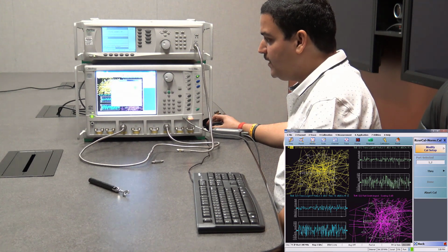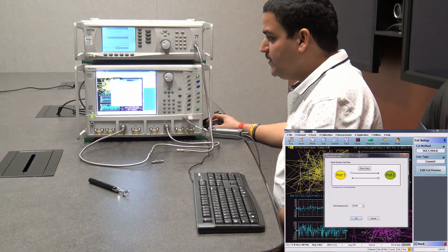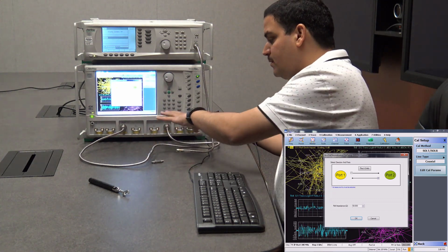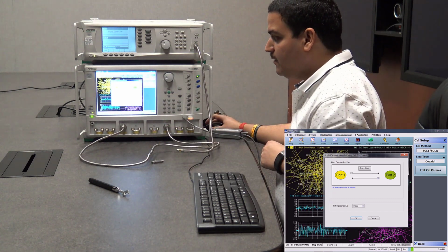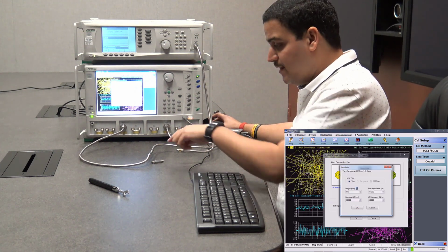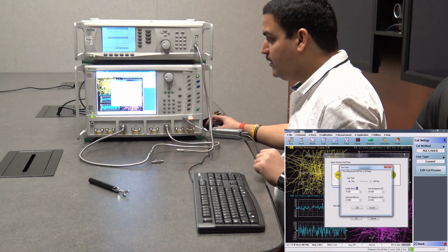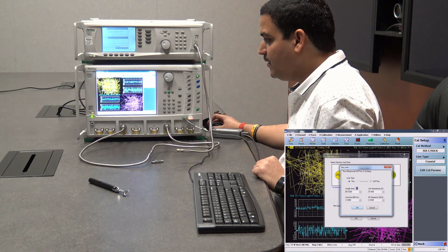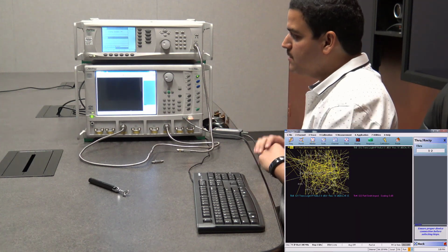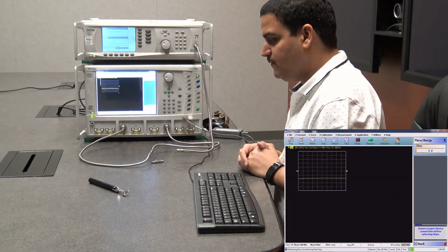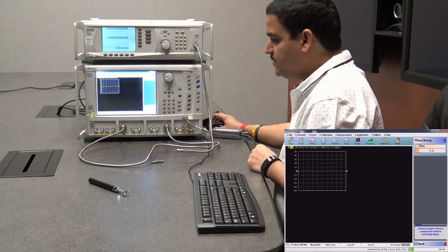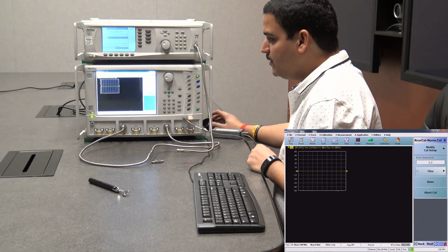You can modify the cal if you want. So yes, we are transferring the power accuracy from port number 1 to port number 2, and you can define the through definition. In our case, 15.82 is the length of this through. So I do that, press OK, and then I go back and do a through. The through is pretty straightforward, and it just does the power accuracy. Once that is done, we are good for the measurement.